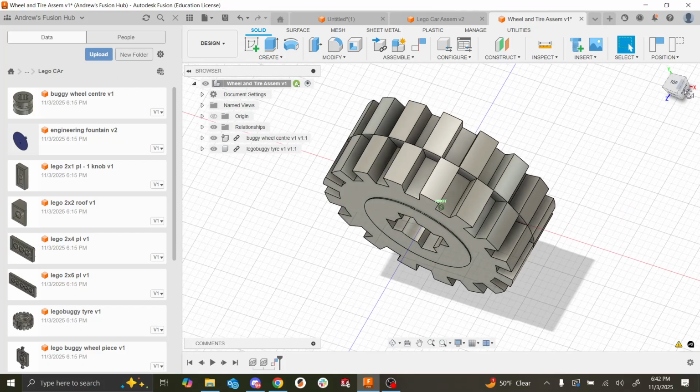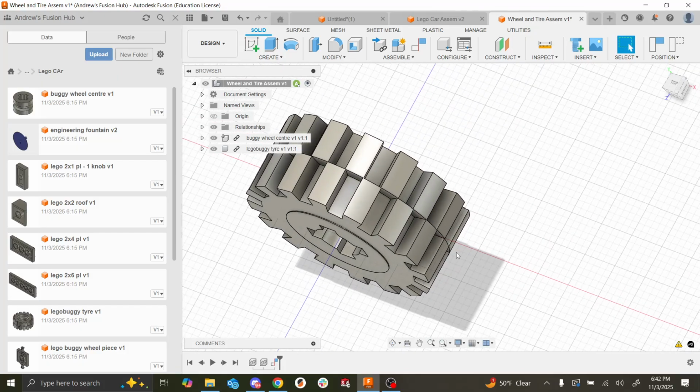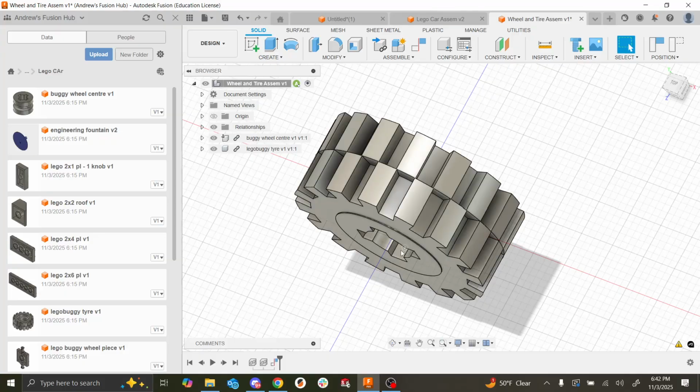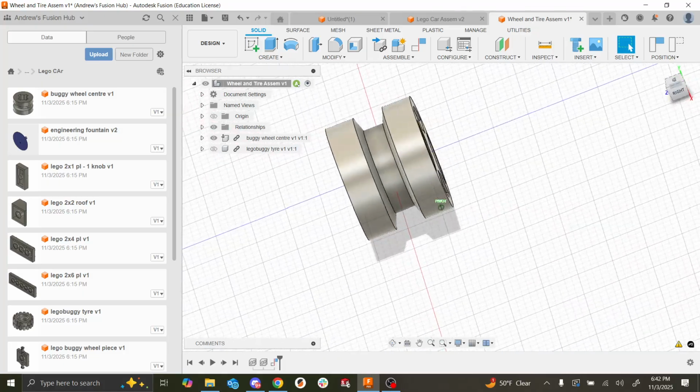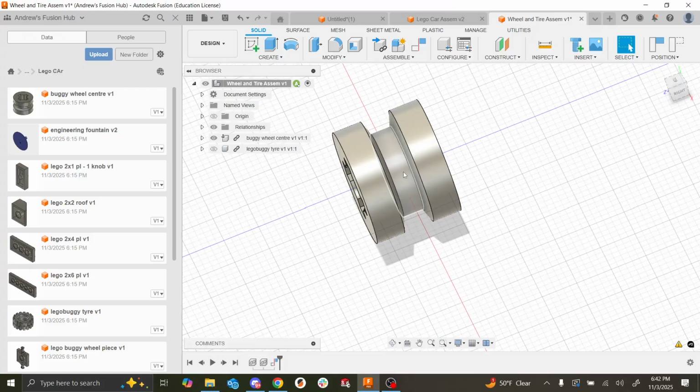Another thing to note, another reason why you might want to do a symmetric extrusion is it leaves those planes that are given to you centered on the part, right? So for the person who designed this, they could have extruded this in one direction, but instead they made the extrusion symmetrical.